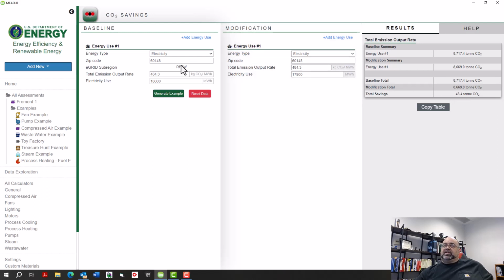So when I go in and I'm starting to track at the larger scale, or even if I say, you know what, let's talk about that one machine, we know what our emissions rate is specific to our eGRID region. And for that motor's consumption, let's say we found a 5 kilowatt loss on a bearing. That's very realistic. So that's going to be 5 kilowatts times 6,000, right? So that's 30,000 kilowatt hours, or 30 megawatt hours.